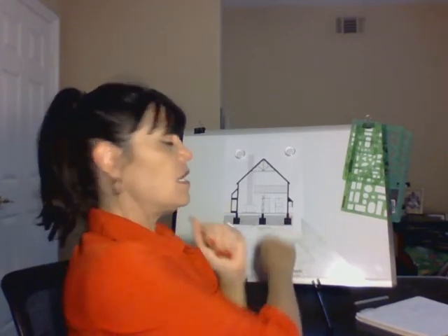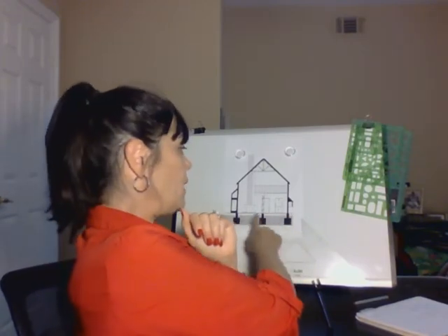Just to give a recap, our sections are basically a multi-plane drawing that we cut and slice vertically. We have to make sure that all of our walls are shaded or filled in and are the darkest lines, and that the ground floor is very dark and heavy. A building section shows footings such as these, shows earth, maybe a concrete platform.